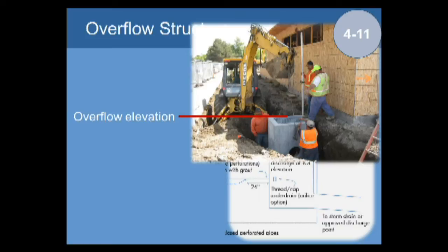The downside of this, and this goes with having lots of drainage management areas and lots of bioretention facilities distributed throughout the site, which you really want in order to replicate the natural hydrology. However, if each one of these has to have a catch basin, the catch basins are about $10,000 a piece installed, and that's just going to be a cost item, depending on the circumstance and the project context. But it's just a trade-off there to consider.